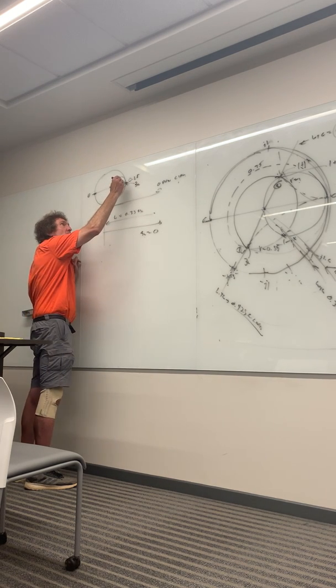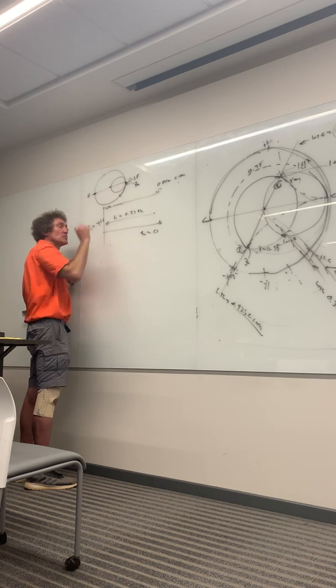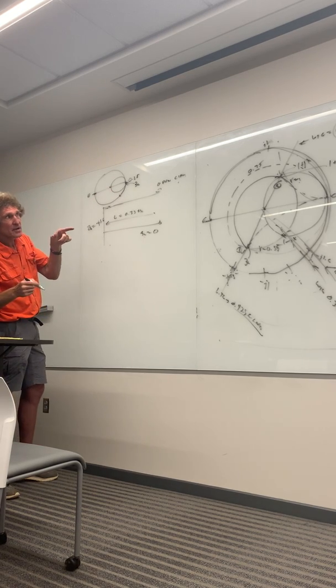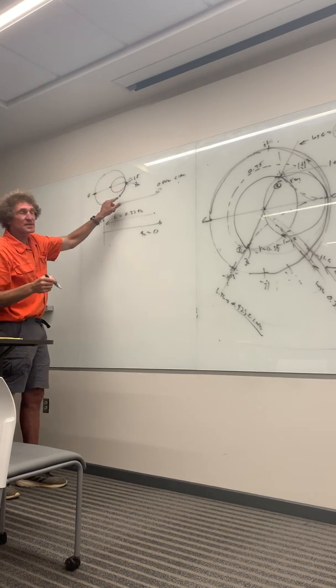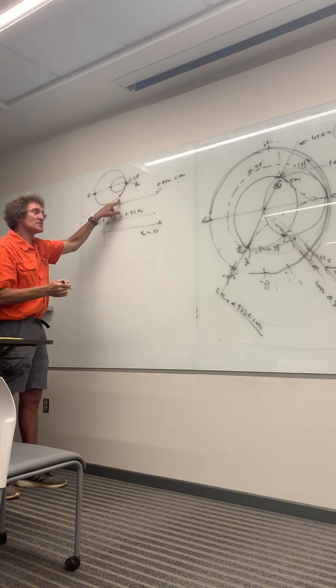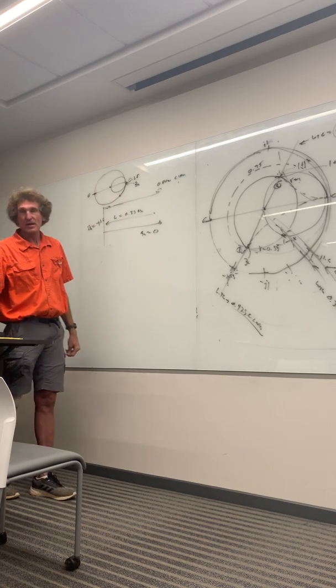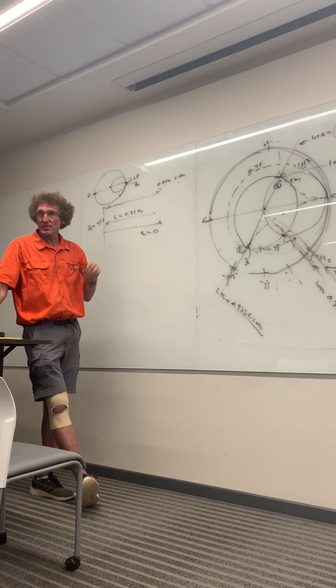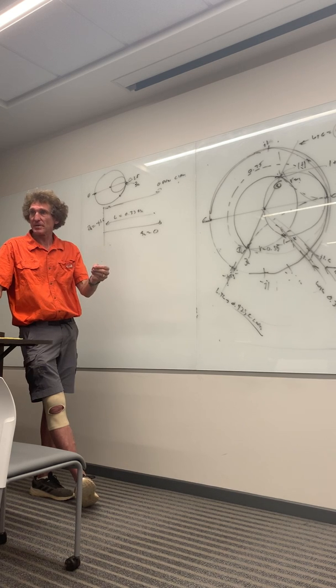Now if I move from there to minus J 1.4, it's exactly a quarter wavelength less than the other one. Do you all see that? So it's shorter. Downside is it also has this open voltage here that can influence nearby elements, and it can really affect them badly. So remember that.